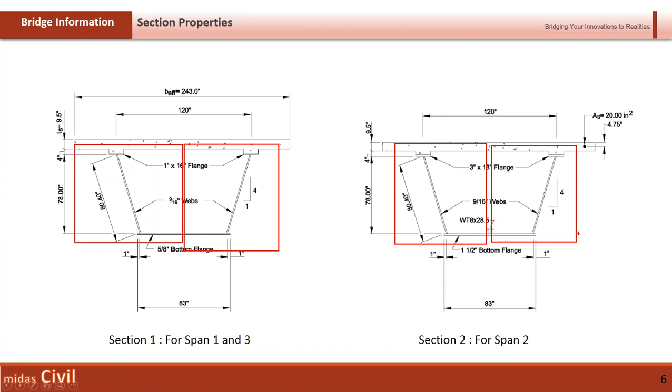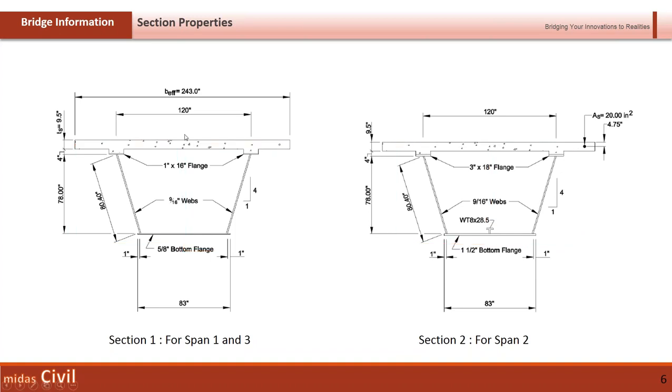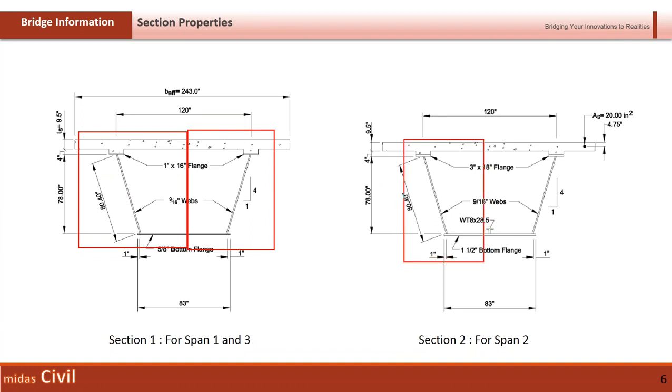If there is a torsion force, then there is an equivalent shear force that is generated inside the webs to resist that torsion. Due to this shear force, the webs might go local buckling, so you have to consider those forces. All the design considerations are very difficult to do if you are doing it by separate I sections.